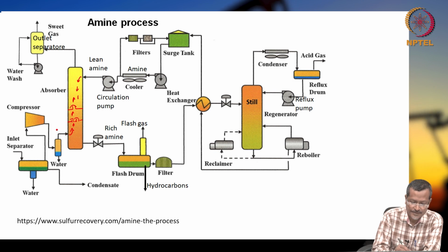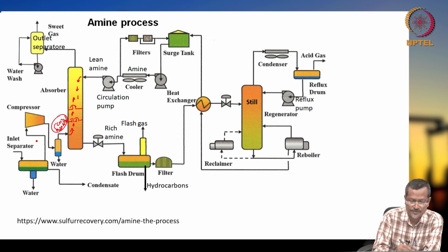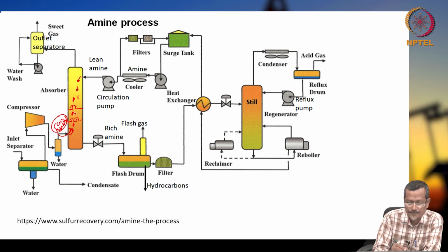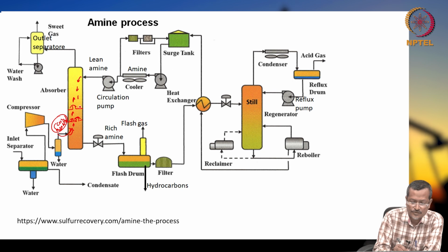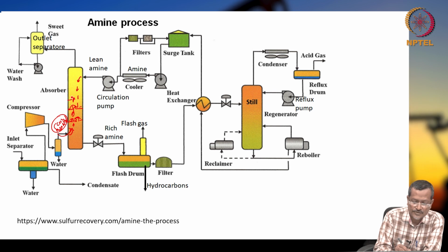So, this is having H2S plus natural gas plus CO2, all this mixture will be there. You are injecting and it will be passing through this tray, these are called trays. This is filled with amine, and when fluid is going, it will be going through this, maybe another tray will be there. So, several steps of trays will be there. One tray, two tray filled with amine solution.